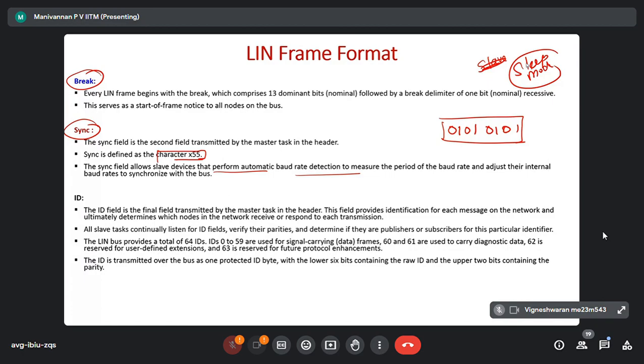So all the ECUs are on. Correct? You went for a 6 months vacation, 3 months vacation, parking your car. When you come back, your car will be totally drained. Because they draw milliamps, for 1 month, 2 months, it is fine, but not longer.